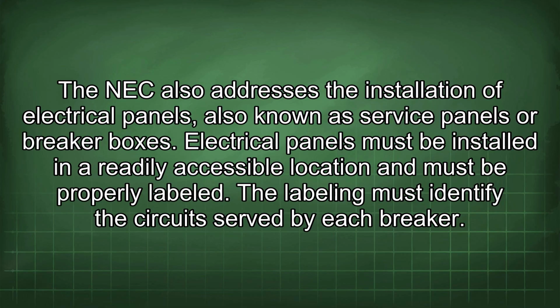The NEC also addresses the installation of electrical panels, also known as service panels or breaker boxes. The electrical panels must be installed in a readily accessible location and must be properly labeled. The labeling must identify the circuits served by each breaker.